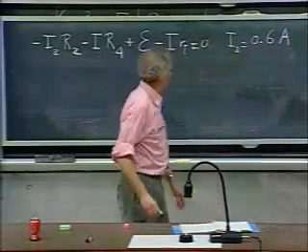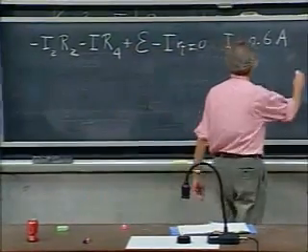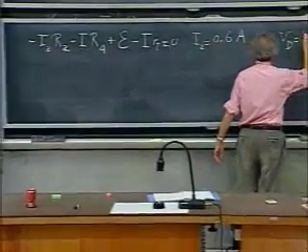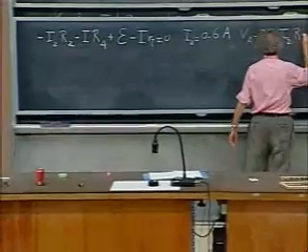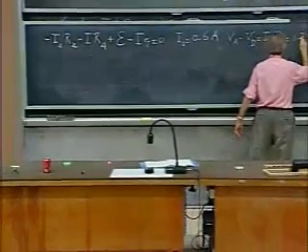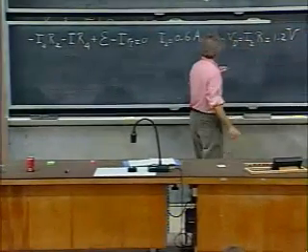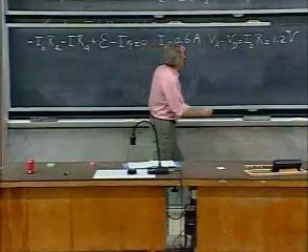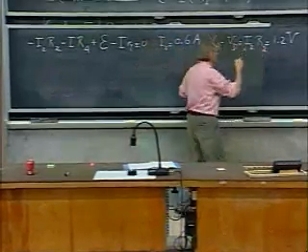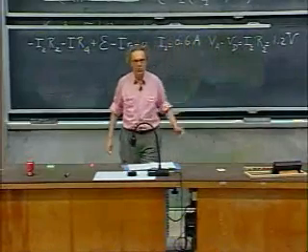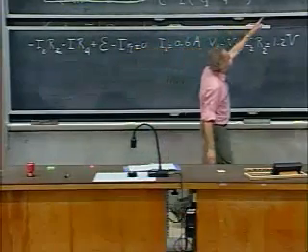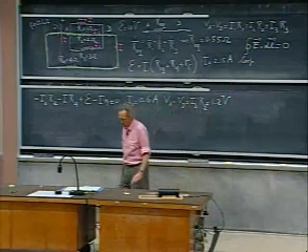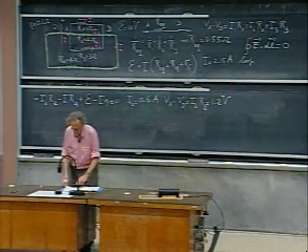And so you know now that VA minus VD, the potential difference, which was I2 R2, is now going to be 1.2 volts. Because I2 is 0.6 amperes, but R2, there's a 2 here, is 2 ohms. So it's 1.2 volts. And so the 1.2 volts is also I1 R1, and it's also I3 R3, so you get I1 and you get I3.